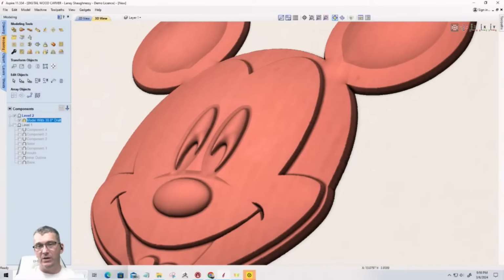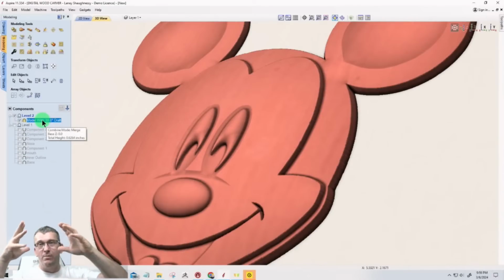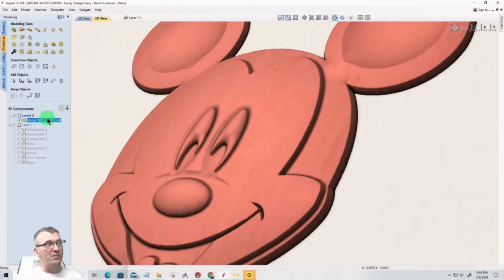I don't delete them. I don't get rid of them or anything like that. But when I did the draft, it created a brand new model, baked everything together, and added the draft to it. So I do not need this model with draft visible as well as all of these visible. So I'm going to start a new level, and I'm going to have my original level. I'm going to uncheck it so it's not turned on. And now I'm working from here.